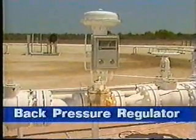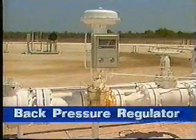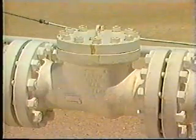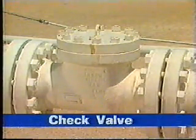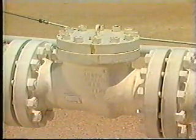Back pressure regulator. A back pressure regulator maintains a predetermined minimum pressure in the meter tube by regulating uneven flow pressures. Check valve. If the pressure downstream of the meter tube becomes greater than the pressure in the meter tube, check valves prevent backflow of NGLs.